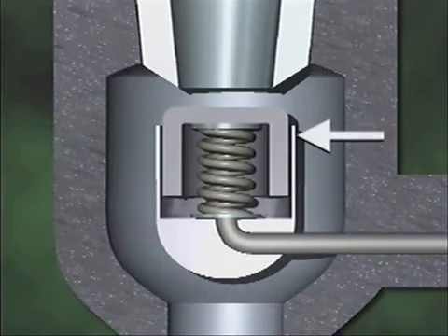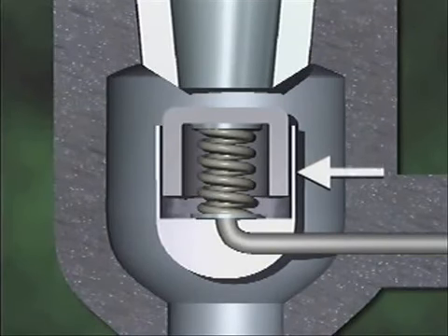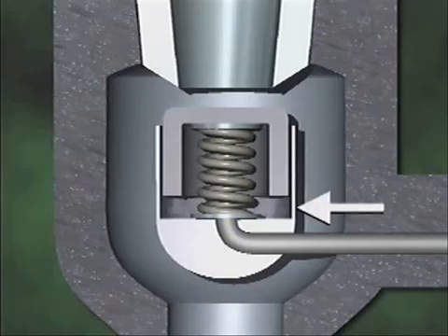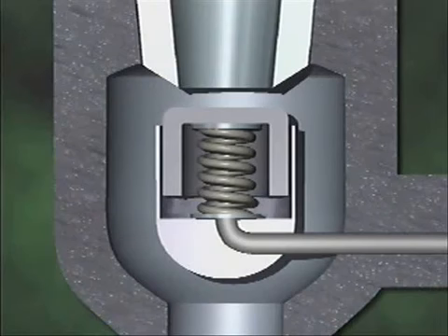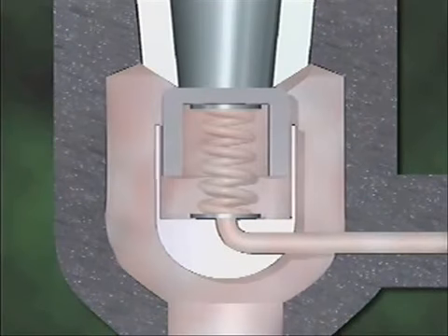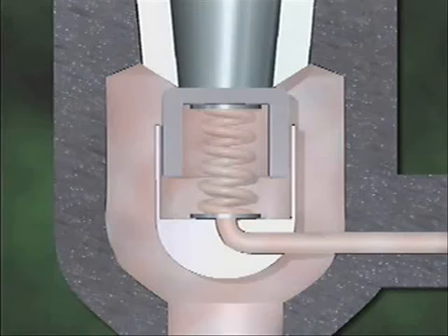The valve also has a disc guide, which is a sleeve that aligns the disc with the seat. A small opening between the disc guide and the disc allows system fluid to pass through from the inlet to the bottom of the main disc. Consequently, system pressure is exerted on both the top and the bottom of the disc during normal system operation. Spring tension is also exerted on the bottom of the disc.